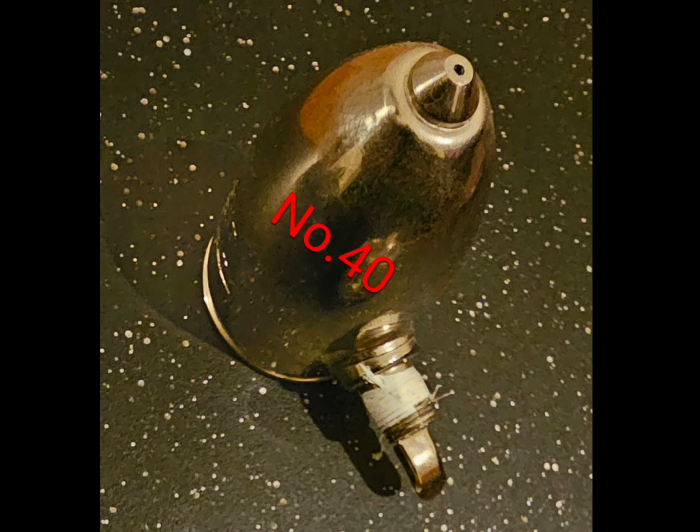What size would you say, and this is on a one pipe system, what size would you say that the service inlet should be on a one pipe system? I'll tell you what it is. The smallest I've ever seen is a 3/4 inch, and there's only one reason why you would find a 3/4 inch service inlet for a one pipe system, and that's pretty much if you're using cast iron baseboard and they don't want to make or run it with 2 pipes.